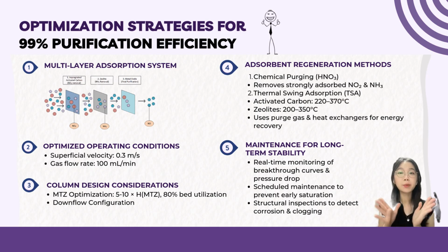So how can we achieve an efficiency of 99%? We refine key parameters mentioned before, which are the multi-layer adsorption system, optimized operating conditions, MTZ, and downflow configuration. Other than that, regeneration strategies should be implemented to prevent adsorbent saturation.